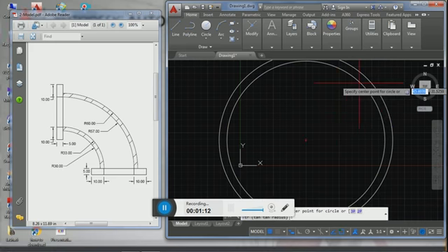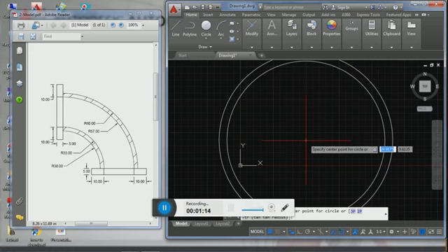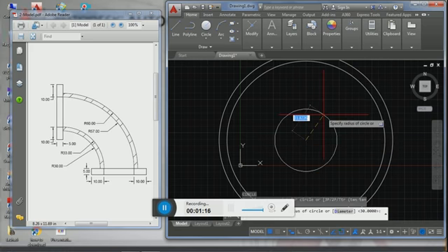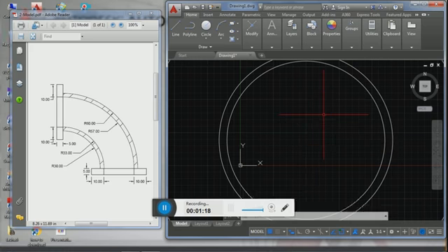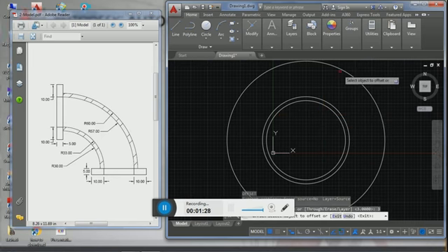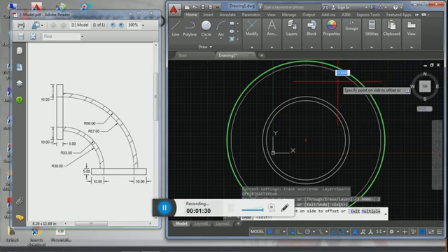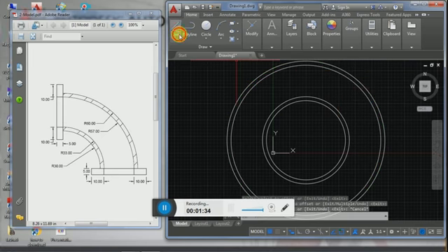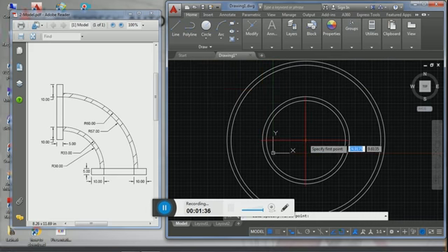Therefore, the circle would be created at 33 mm. Then create a 60 mm circle on the same center. Then take offset about 3 mm inside from the outermost circle.